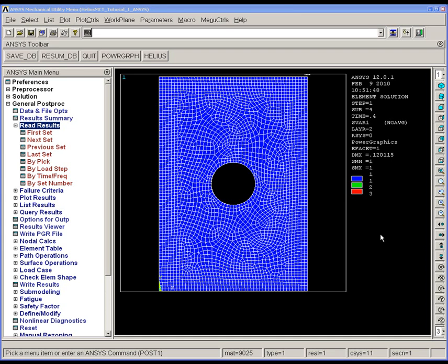Helios MCT provides additional output variables that aren't available in a conventional ANSYS analysis. These output variables provide insight into whether or not the matrix or fiber constituents have failed, and also show how these failures propagate during a composite analysis. These output variables are available as state variables, or SVARs, within ANSYS.